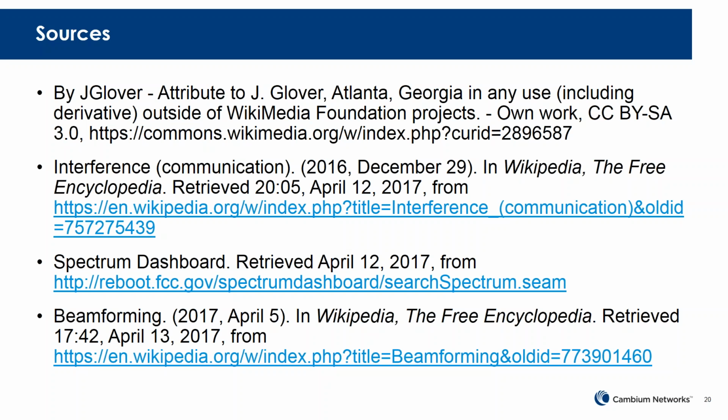For instance, if you can find a channel that's cleaner and you can reuse that channel, and maybe the noise floor is 20 dB better than another channel that you would be forced to use if you didn't use GPS synchronization, then in that case, GPS synchronization will be better than beamforming, because your gain for beamforming, I think, is at most about 10 dB. So GPS synchronization is basically helping you find cleaner channels in a sense. It's a tough question.